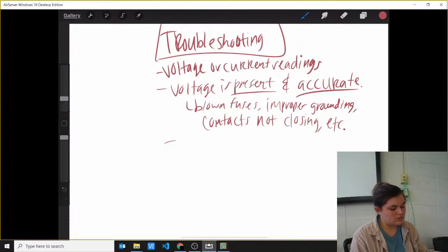Alright, I'm about to read you just one last thing and then we'll be done, okay? Motor drives provide energy savings when used with variable speed and variable torque loads. Motor drives are commonly installed on pumps and fans and HVAC applications. When a motor drive is installed to control a pump or fan motor, the speed of the motor can be varied to control the flow rate of the pump or fan, allowing less energy to be used.